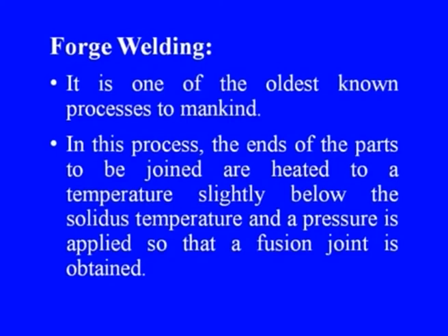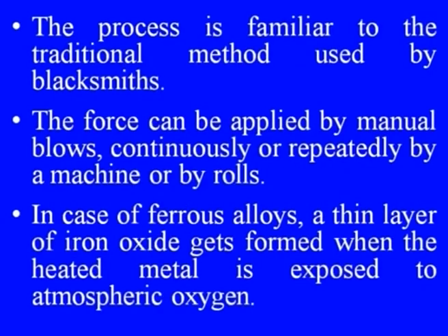It is one of the oldest known processes to mankind. In this process, the ends of the parts to be joined are heated to a temperature slightly below the solidus temperature and a pressure is applied so that a fusion joint is obtained. The process is similar to the traditional method used by blacksmiths. The force can be applied by manual blows, continuously or repeatedly by a machine, or by rolls.